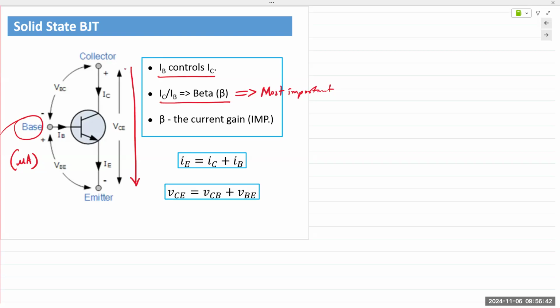We are implanting millions and billions of atoms in there, not even millions and billions, 10 raised to 15, 10 raised to 16, 10 raised to 18 atoms per centimeter cube. You'll remember from chapter 2. So we cannot control the fabrication process down to the last single atom. And so there's always going to be variations in the exact same device.